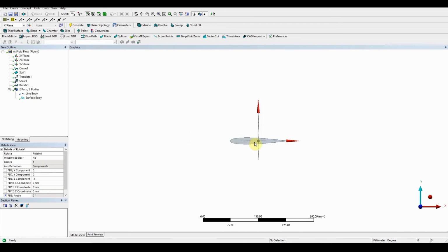So what that means is we don't need to generate different models for different angles. We use one geometry file, and we have the angle of attack as a parametric function in order to give us all of our results. So this speeds up the whole process.